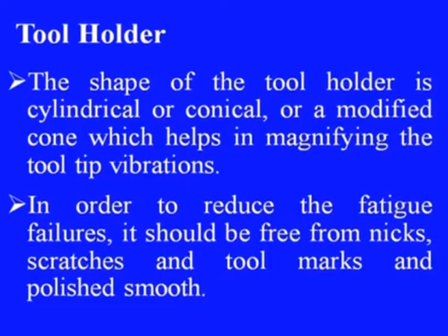Let us look at the tool holder, which is considered to be one of the important components in this system. The shape of the tool holder is generally cylindrical or conical or a modified cone which helps in magnifying the tool tip vibration.